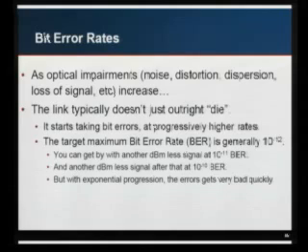And that's where forward error correction really makes a big improvement. At a point where you might have had a really hideous bit error rate, you're able to compensate for that with FEC. And that lets you get a lot more receive sensitivity out of the whole system.